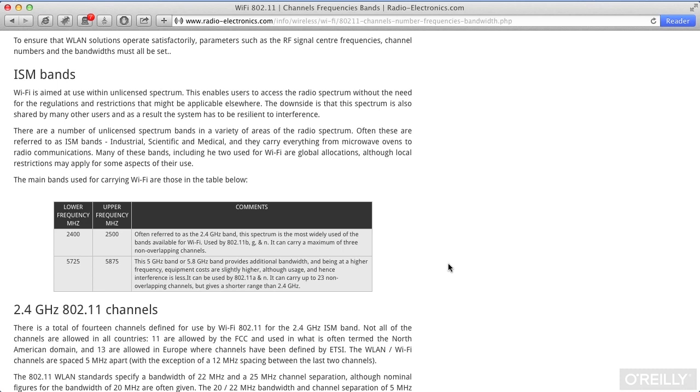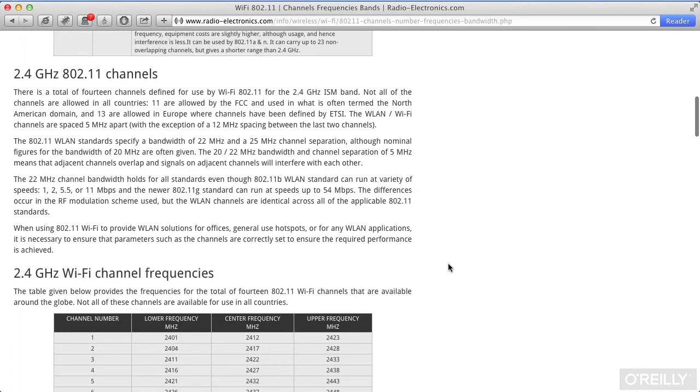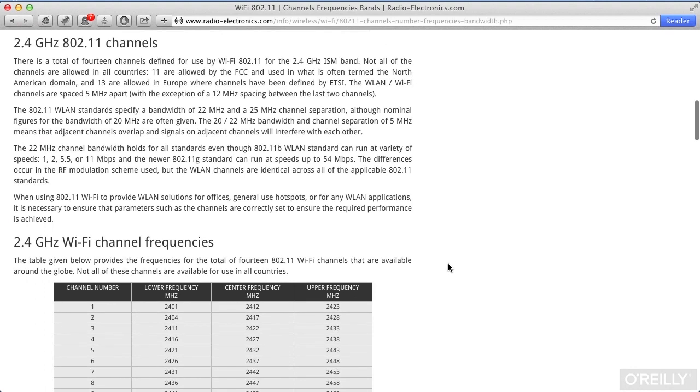You will see an awful lot of signals in that 2.4 gigahertz range, and that range is really becoming cluttered. One of the issues you'll sometimes see is a cordless phone that's acting up and really old, or a microwave oven that's really old. Some of these older electronics operate somewhere near the same frequency range that your 802.11 Wi-Fi systems are using. You may start to see spikes into that same frequency range, and you could end up seeing degraded signals as a result.